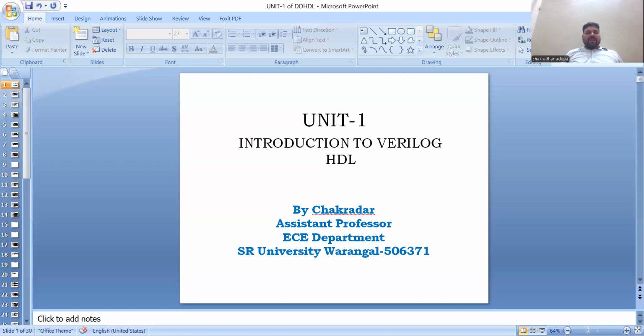For example, 4'B1111 indicates a 4-bit binary number. Here 4 means it's a 4-bit number, B means the format is binary, and 1111 is a 4-digit binary number. Second, if you observe 12'HABC, 12 indicates a 12-bit number, and H stands for hexadecimal, whereas the number is ABC, and each digit is represented with 4 bits, that is 12. ABC is a hexadecimal number.